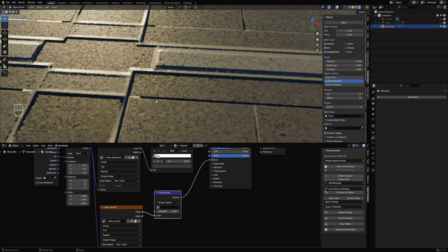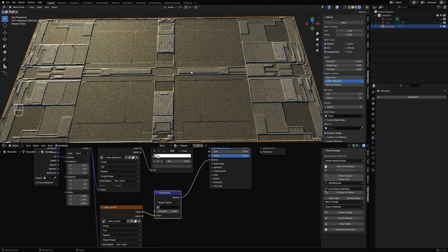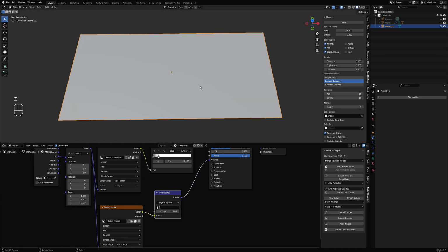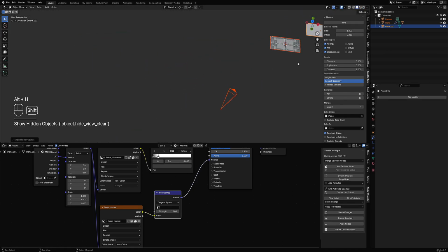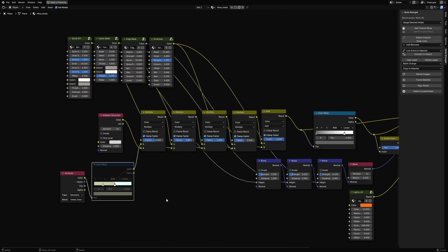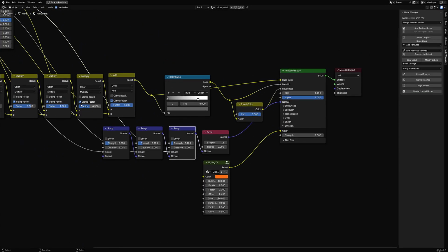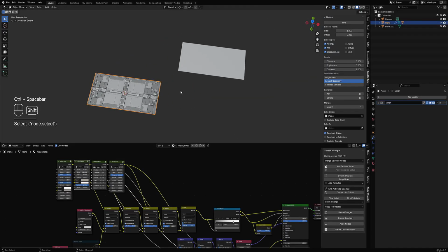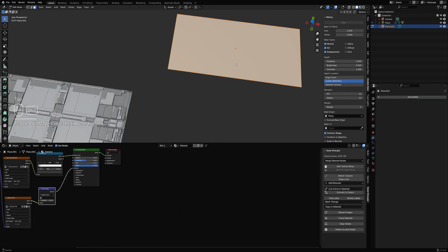And it has that grainy look. Oh, I know where the noise is coming from. That is from the bump from the original shader. Look, we're using bumps coming from these shader nodes, but because the map is too small to incorporate all the details from that bump from the original object, it's coming up as noise.